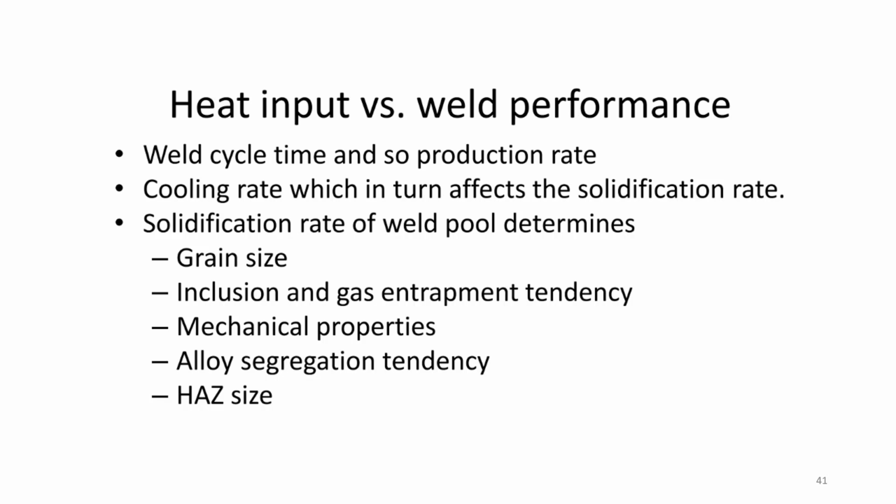Heat input versus weld performance. So weld cycle time and production rate are related. Then cooling rate, which in turn affects the solidification rate. Okay, so the higher the cooling rate, the higher the solidification rate. So if the solidification rate is very high, your grain size will be smaller.